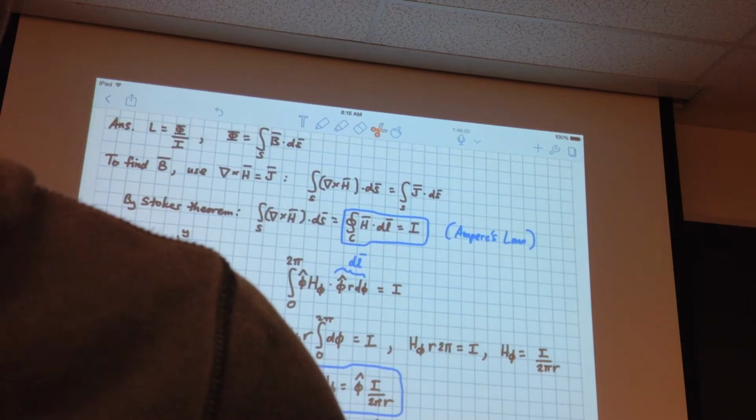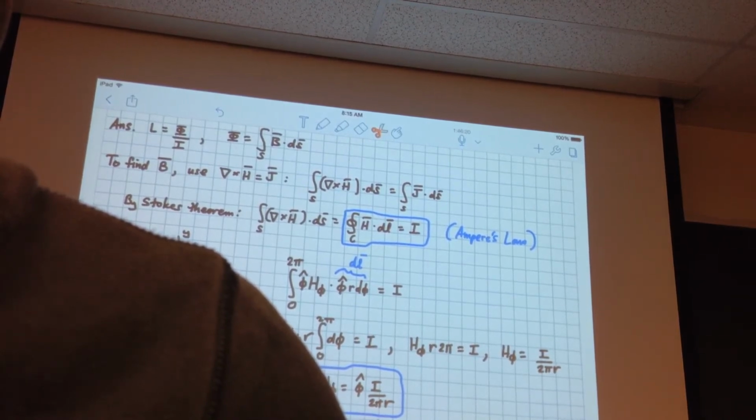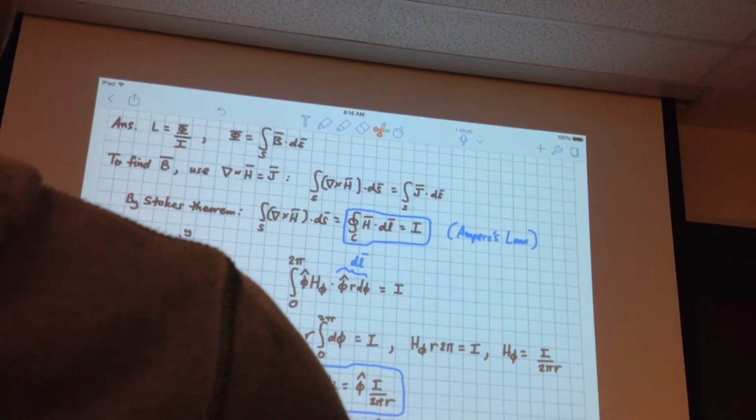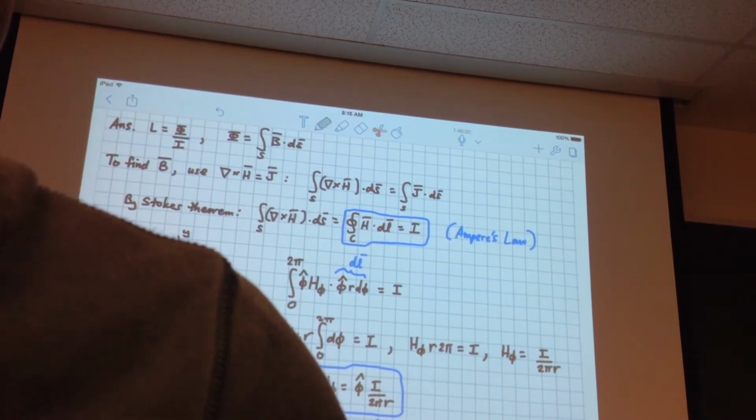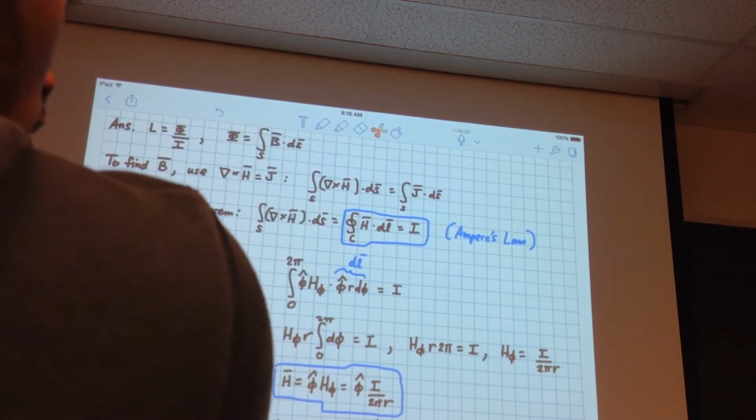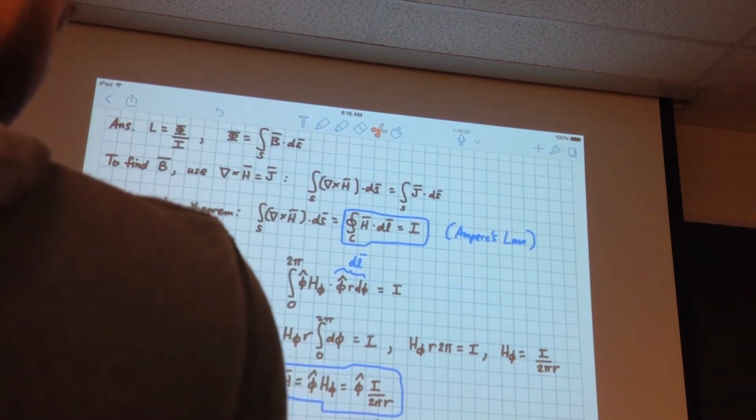One is the contour for the magnetic field, and then the other one is this red line, which represents the surface of our infinitely long coax. So you have to kind of imagine the current I is coming out in this direction, out of the page. It's going out to infinity, and then it's coming across that infinity and coming back on the outer conductor. Okay.